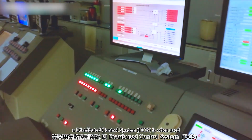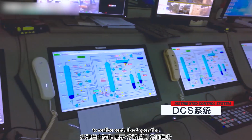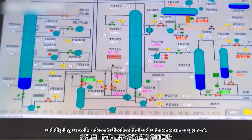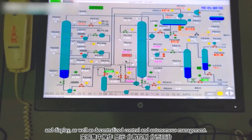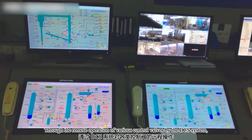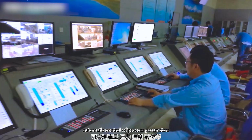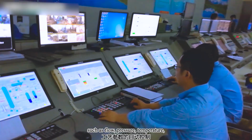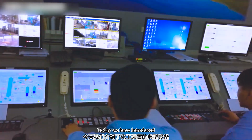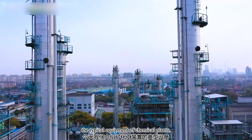A distributed control system, DCS, is often used to realize centralized operation and display, as well as decentralized control and autonomous management. Through the remote operation of various control valves by the DCS system, automatic control of process parameters, such as flow, pressure, temperature, and liquid level can be realized. Today we have introduced the typical equipment of chemical plants.